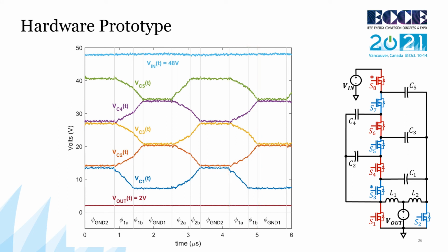phase. Now, importantly, notice that here our fly capacitors are operating with a very large voltage ripple, over a full order of magnitude larger than that previously demonstrated. This indicates highly effective use of these energy transfer elements, with much smaller capacitors being required in practice. Additionally, all capacitors see smooth and continuous voltage transitions, verifying that they are all being soft charged with high efficiency.